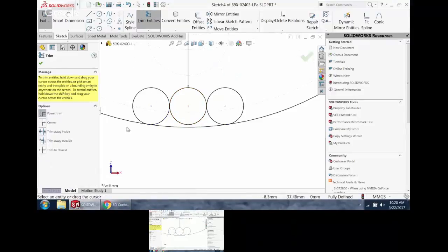So let me show you that again. Trim here. There we go. Brings it all back. And you can continue trimming. The trim tool also works as an extension tool. I don't know if you knew that either, but if you're in the trim tool and you click and drag something and drag it past, you can make it just longer or shorter. It will snap automatically, like when it hits another arc or a line as you're doing extend. So it truly is a trim and extend tool.